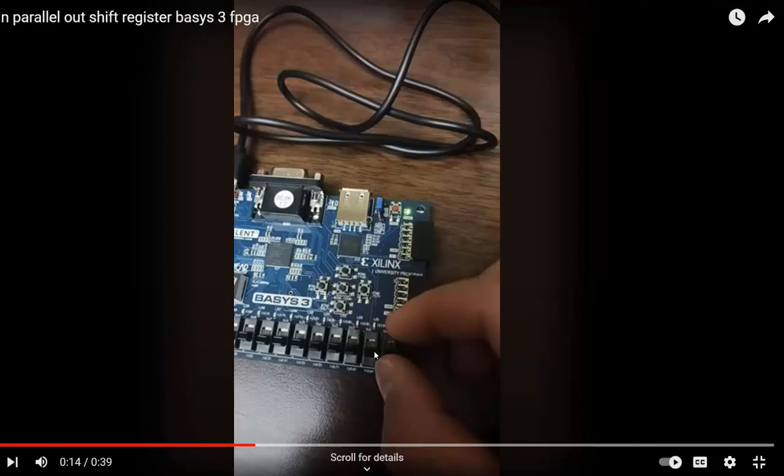It's very similar to data transmission, for example, serial or UART. It's usually 8 bits, just 1 byte. It sends 8 bits. When it's ready, it turns on a flag and makes that data ready, so all the other registers can read it. It's very similar, but we are not turning on any flag. It's just 4 bits, and after the 4th rising edge it should show the result on the LED. So it should show 1010 on the LED. Is that clear?